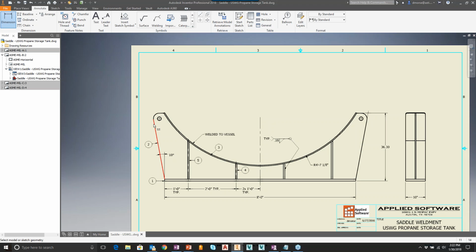So in the dimension tool, select, right click, intersection, then I pick that line. Then I'm going to come over here and select this line. You can see it's giving me the apparent intersection of the first two selections, but again, Inventor always wants to give me a preview based on my selection.